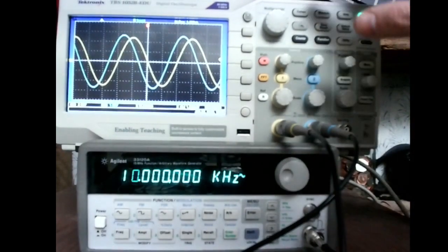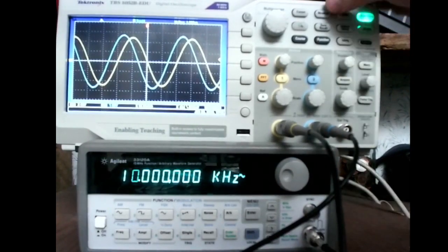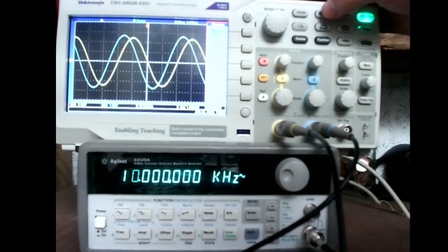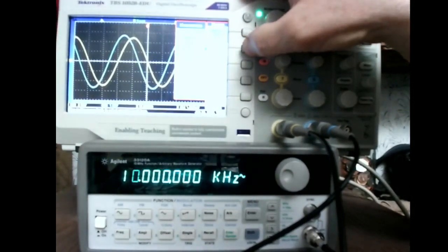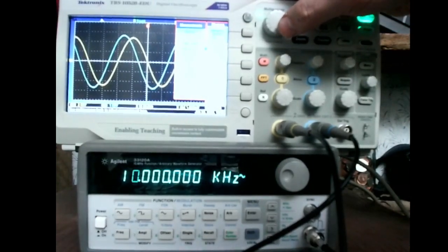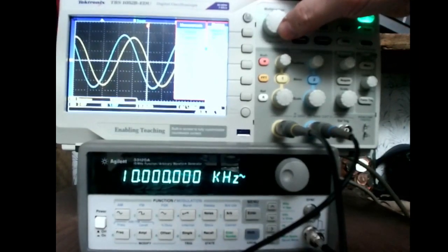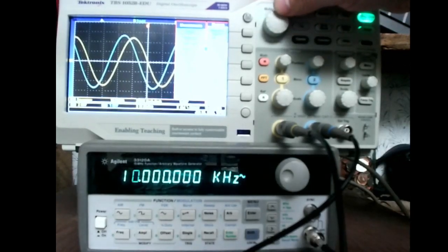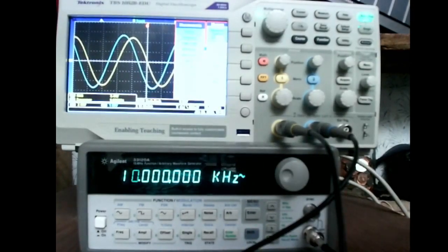Now these digital oscilloscopes have a couple of really nice features on them. One of them is this button here called measure. With measure, you can click on that and say, I want measurements from channel 1. And then you can pick out what measurements you want from channel 1. Do you want to see what the frequency is? You can scroll up and down and say, yes, I want to see the frequency. I want to see the peak-to-peak voltage for channel 1. I want to see the RMS voltage for channel 1. And a lot of other settings that you can select here.